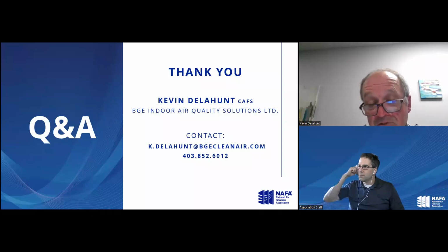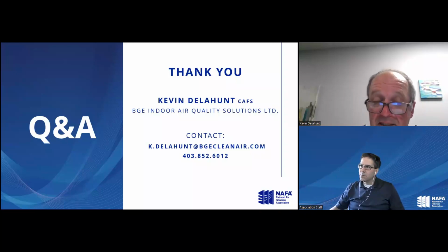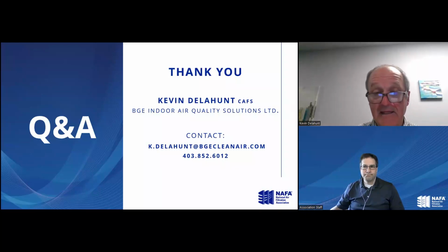MERV 11 to me was a compromise. So we compromised at MERV 11. We're asking that any future design start at least at MERV 13. I think an upgrade of this document, which will happen in the next couple of years, will probably go to MERV 13, because that will start to reflect the interest in the marketplace. If new systems are all designed for MERV 13, there'll be more and more MERV 13 filter systems in residential HVAC.